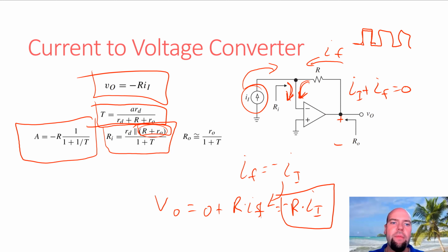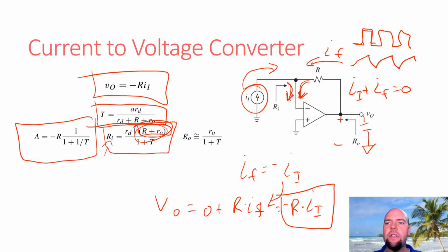And so this output resistance, which is actually output impedance, if there was undesirable capacitance here, that capacitance shows up at the input. And then what you're going to see is basically your nice clean signal starts to look like this, right? So your input current is now unintentionally going to be charging and discharging this Miller effect capacitance on the input of that.